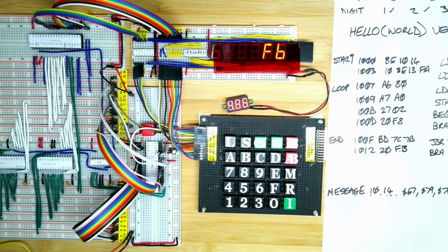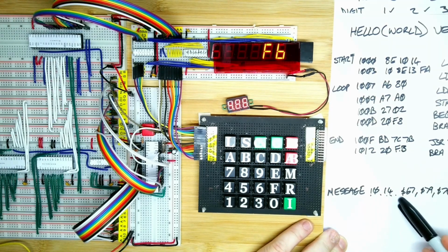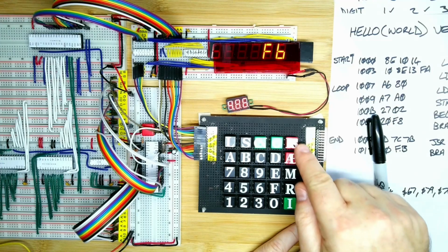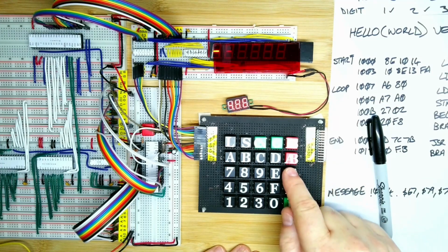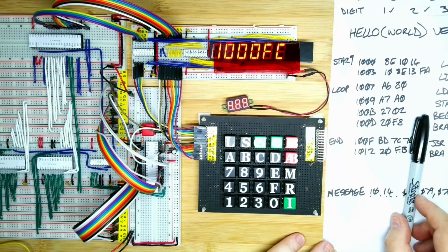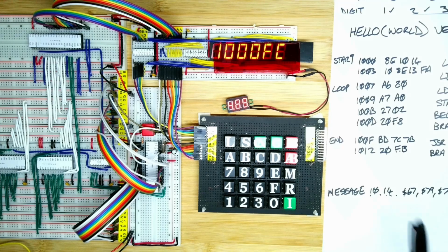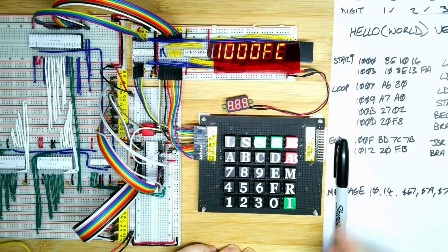And that sounds about right because it's only a couple of bytes that we're going back, whereas F6 would be almost 10 bytes that we're going back. Okay, so looks like we've got everything there. So what we can do now is if we just now go to 100, we're going to type this in, and then we'll go back and check it, and then we'll see if we can get it to run.